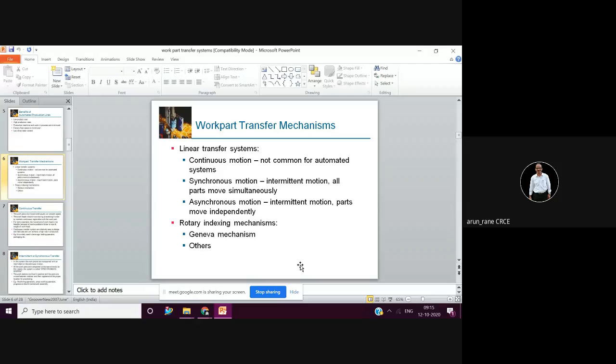That may not be the case in rotary indexing. If a worker from station number one has been asked to help the worker at station number 10, the travel length is less in case of rotary, and in case of U and S also the travel length will be less.